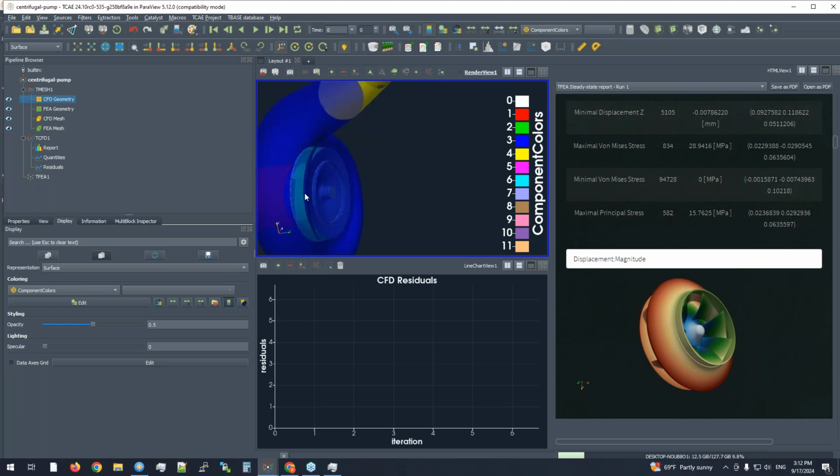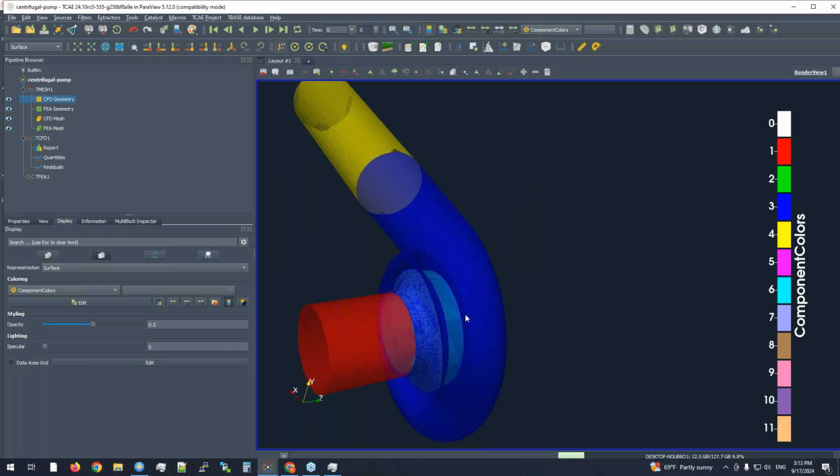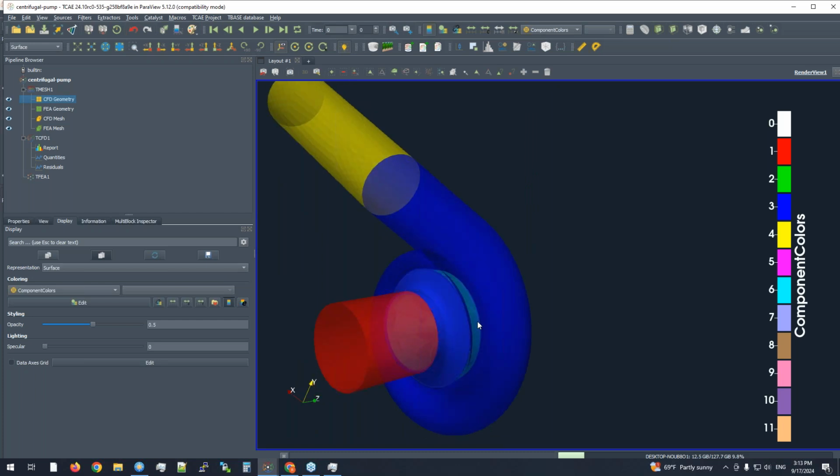It's a more complex geometry, but if the patches of your impeller have the holes, include the holes, then the workflow remains the same. You have to have the whole impeller, right? Also including the backside and everything, have it in fluid. As I am showing right now, this is the case where the leakage is also included. So the whole solid of the impeller is included in the simulation, like the wetted part. And if there are holes which go from the front part, from the hub to the shroud, then they are there, and the workflow remains the same. So it can be done.